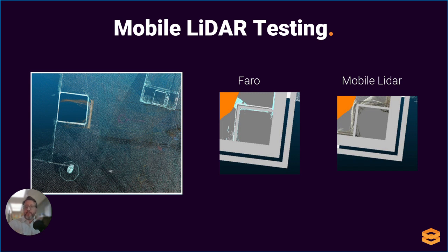So I was out in the field, and I was able to use the mobile scanner. I'm familiar with Faro scanning as well, so we were able to do a comparative study to see feasibility. And it ended up being that, with generation 1 of the phone mobile scanner, there are some inherent problems, drift, etc., that you don't get with a terrestrial scanner like a Faro.